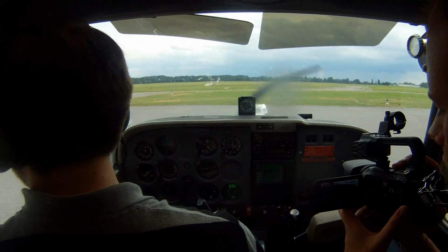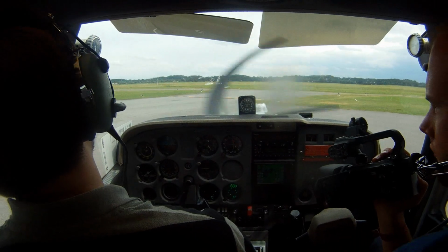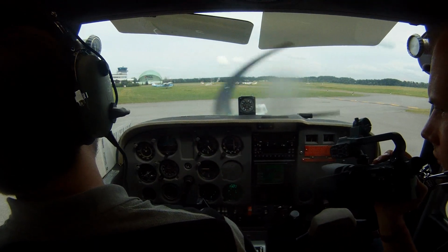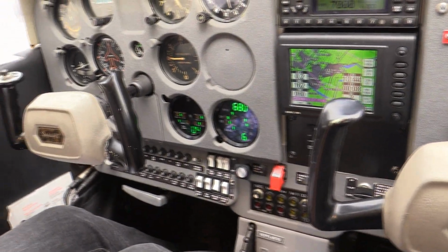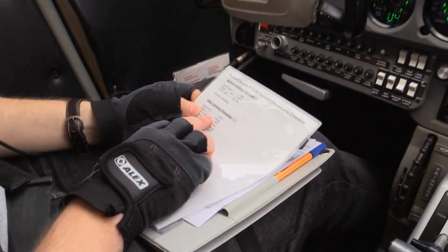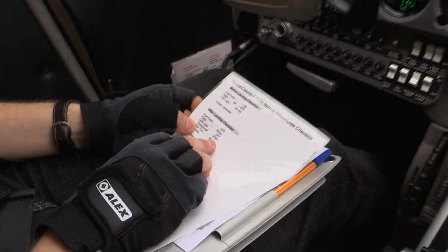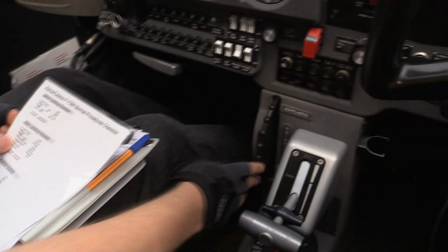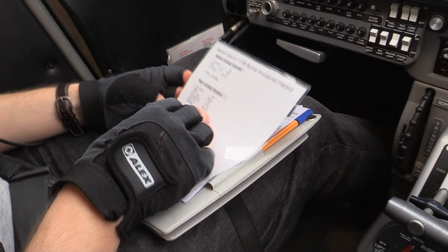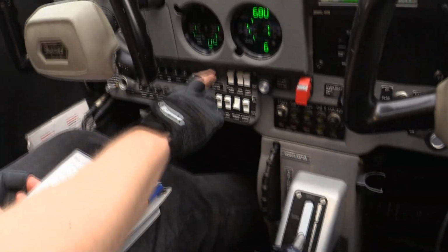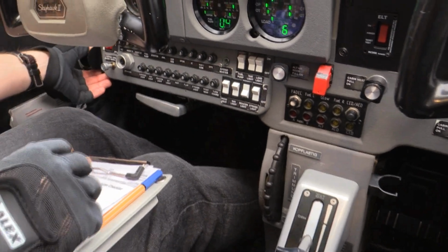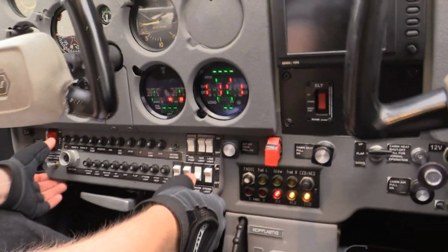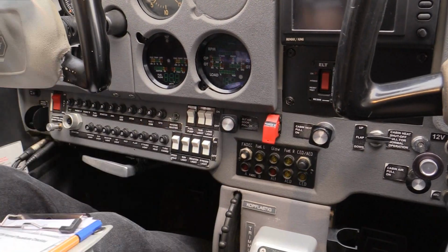Okay, let's just turn the aircraft around here. And shut it down. Let's go through the checklist. After landing checklist, the fuel pump is off, flaps are retracted, landing light is off, transponder is standby, step trim is neutral, and the strobes are off. Shutdown checklist, avionics off. And the nav lights are off, the main bus off, engine master off, and that cuts our engine beacon off, battery off. And that concludes our flight to Essen.